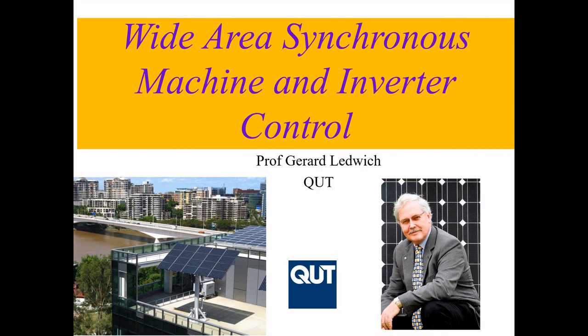Okay, thanks, Matt. So I can see there's a question: does control according to a calculated remote source reference encroach on inverter rating, as PQ isn't controlled explicitly at the inverter terminals? The injected current is being controlled at the inverter terminals. I would suspect that maintaining a voltage profile is important, and that was the point of my diagrams of phasors. So an overriding voltage magnitude would probably be a good idea, but the basic controls of magnitude of current are probably more robust than pure voltage control at the remote area, particularly when you're susceptible to oscillations.